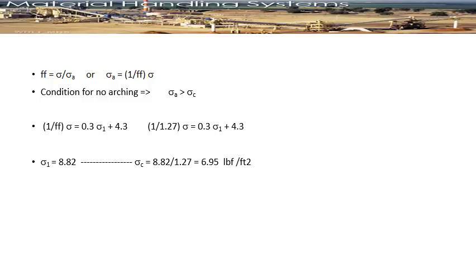Now we need to find the value of the diameter, so we apply the equation we had in the lecture notes. It's going to be H theta multiplied by sigma critical, multiplied by 47.88, which is the factor to change the sigma critical value from pound force per square foot into Pascal, which is Newton per square meter.